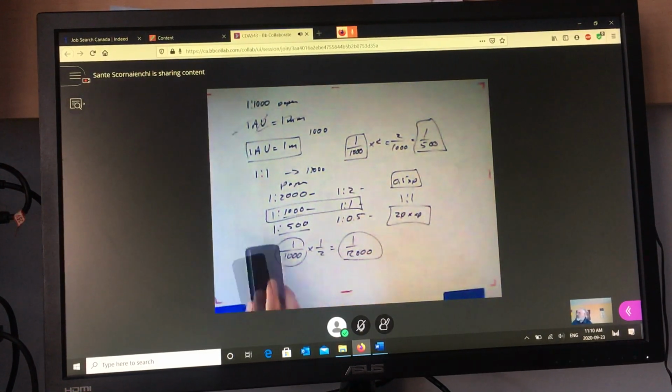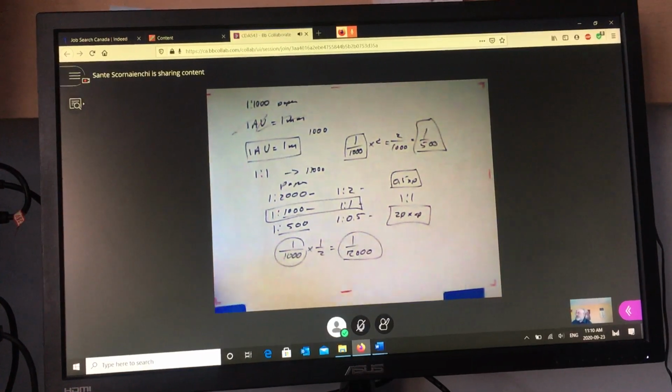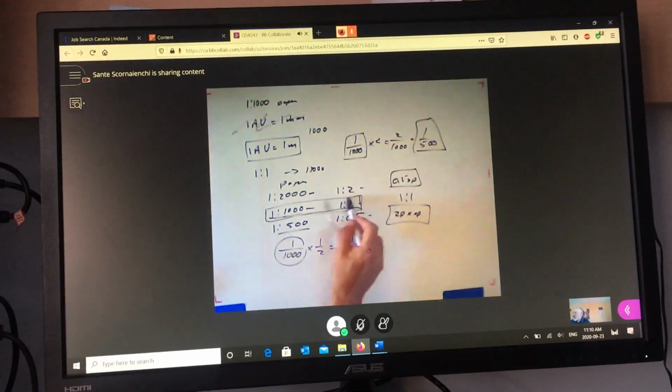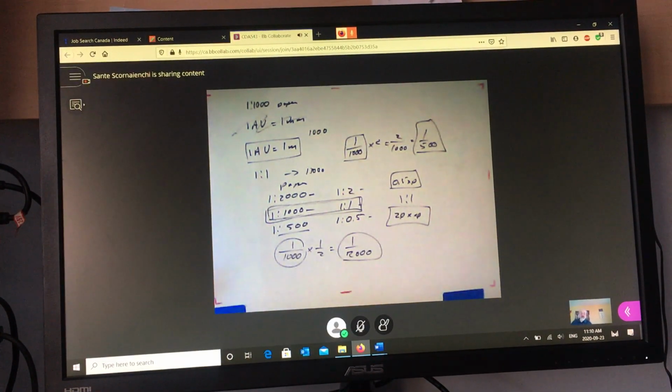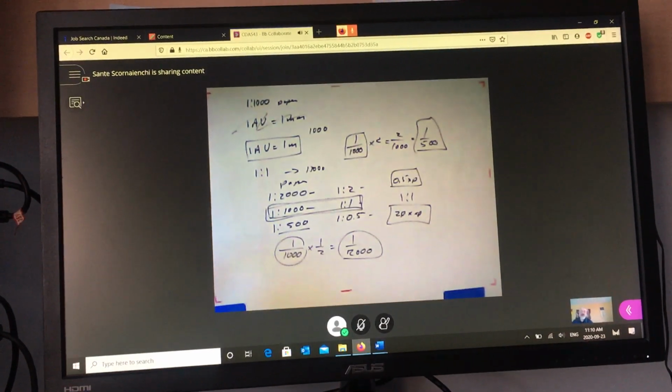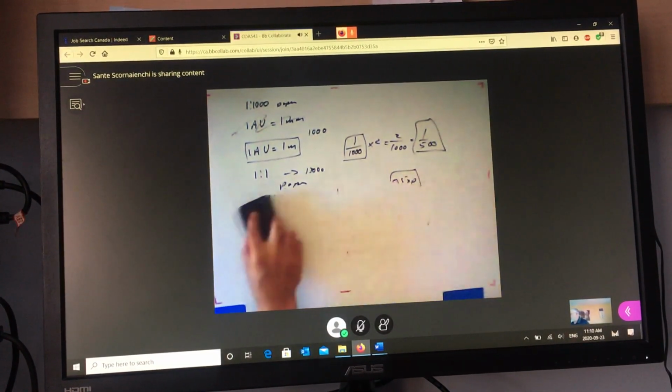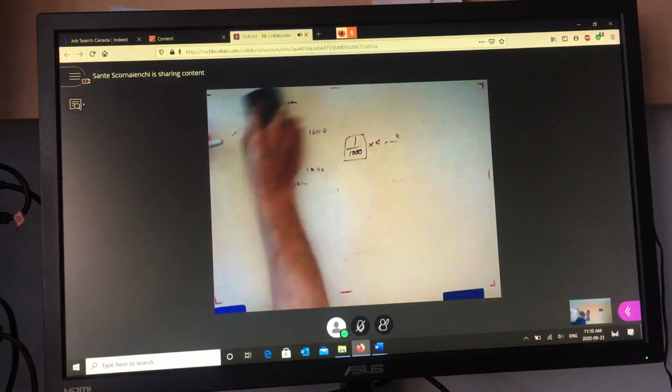Okay? So we're going to manipulate the zoom factor, not the plotting scale. We will always plot at 1 to 1. The good news is you don't have to do anything. Just open your drawing and print it. You don't have to change any of the settings. All you have to manage is the zoom factor by choosing the appropriate scale that you want on that list that I showed you. And I'll show it to you again. Okay, we'll get right back to that.